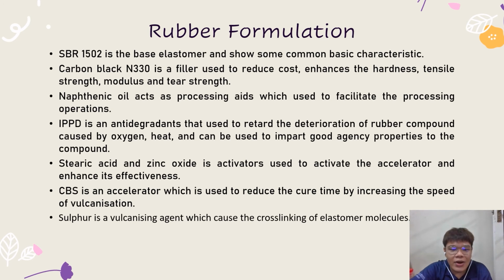Moreover, stearic acid and zinc oxide are activators used to activate the accelerator and enhance its effectiveness. CBS is an accelerator, used to reduce the cure time by increasing the speed of vulcanization. Sulfur is a vulcanizing agent which causes the cross-linking of elastomer molecules.